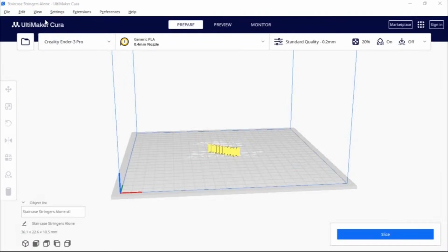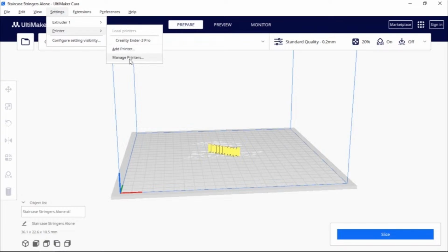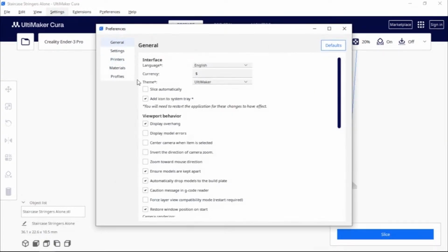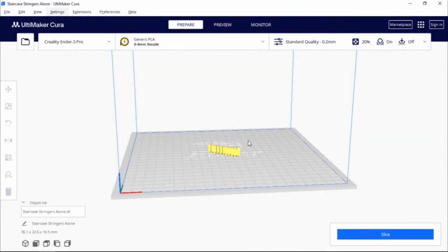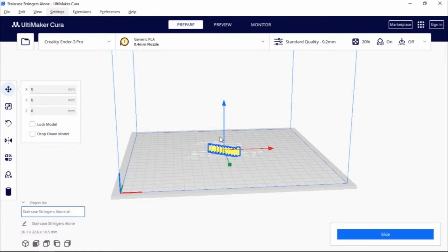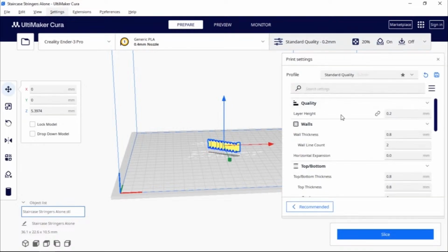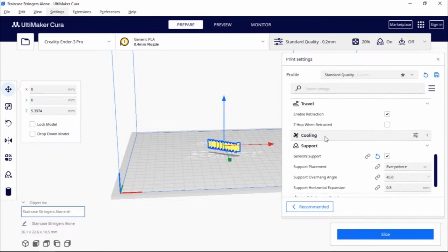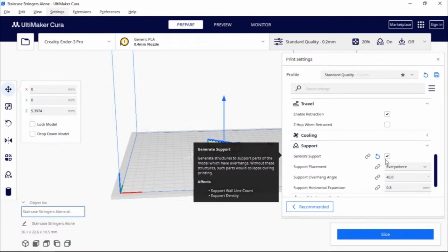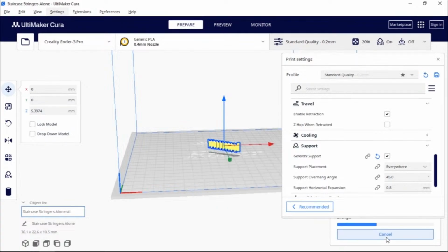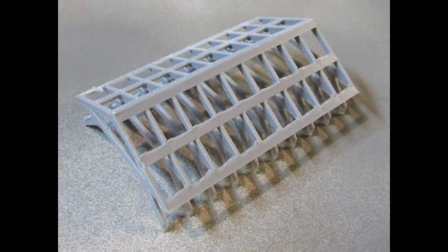When printing the stringer staircase, I had difficulty removing it from the build plate. It's delicate and kept breaking along the handrail holes or on the ends. I ended up printing it on its side and elevated 5 millimeters above the build plate on supports, which worked but did require some cleanup of the supports. You will probably need to enlarge the holes in the staircase in order to place the handrails. I used some numbered drill bits for this and worked gently. This generator is not great, but it's something, and I'm looking to improve it as time and ideas permit.